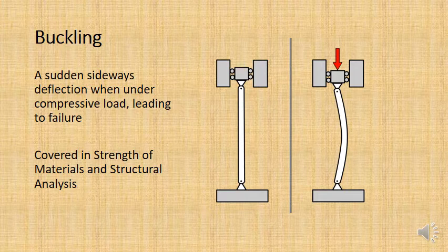Now, when it starts bending like a banana, you basically have flexural loading to a degree. On the outside of that timber, you're going to have tensile loading, and on the inside you're going to have compressive loading. And so usually the timber will snap long before you get to the compressive load, because you basically have a flexural load going across it, with tensile loading moving over to compressive loading.